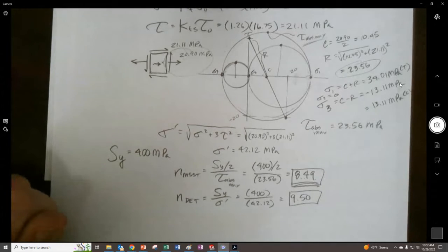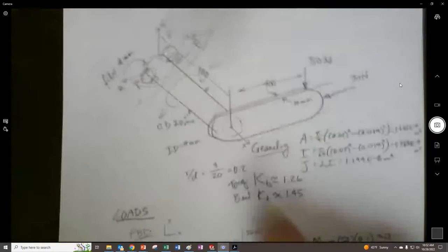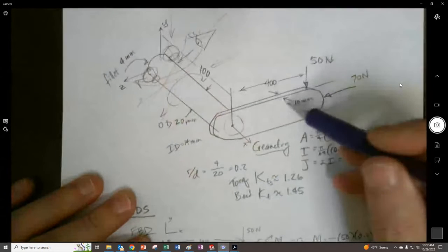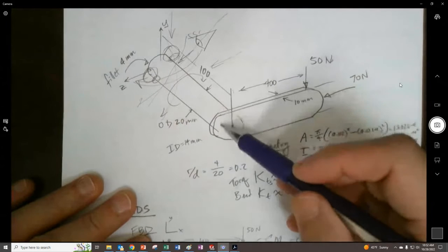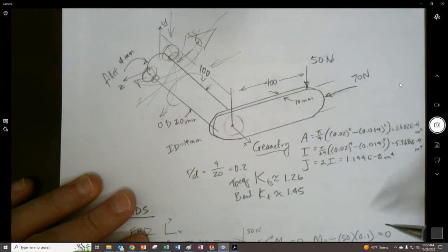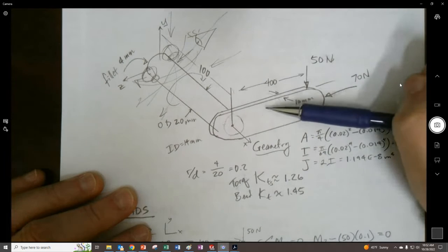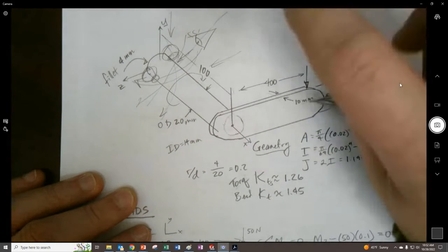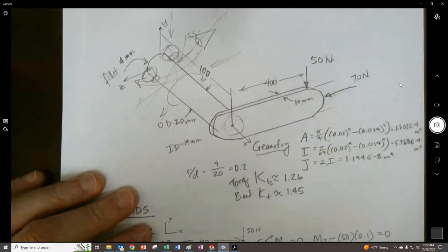It kind of leads me to also want to mention, just in terms of real engineering, we're only looking at this one spot, but I'm a little concerned about this thing. How thin is this piece right in here? Or what about this joint in between these two spots? Is there anything particular about this? And it would be maybe particularly challenging to address, but what about the buckling of this piece right there, in terms of the twist buckling that could happen because this thing's a thin plate? I've got to have some questions about that, right?